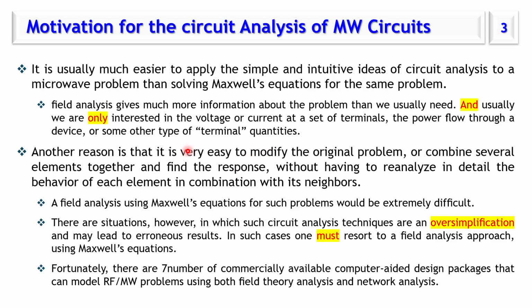Why do we need a microwave circuit analysis tool? Why don't we go for field analysis, using Maxwell's equations? There are a couple of reasons for that. For example, Maxwell's equations and field analysis are very comprehensive, and usually give us a lot of details that we might not be interested in. For many microwave circuits, what we are interested in are a couple of parameters at the boundaries, or what we call the ports of the circuit.